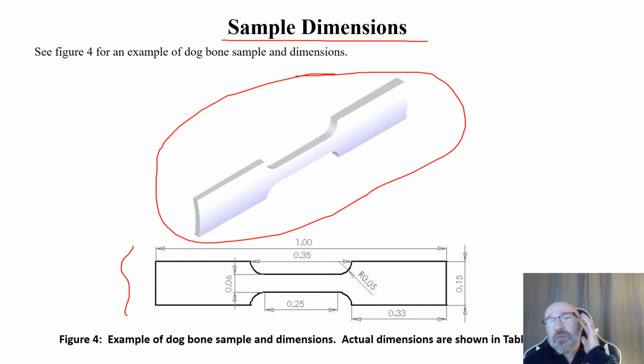And this is information that is important, one, for you to understand exactly what's going to fit in your case. Okay, here's a physical thing, it's curved. How big of a sample can I get out of this without having that radius on the inside of this be an overbearing effect there? How many specimens can I get out of it?